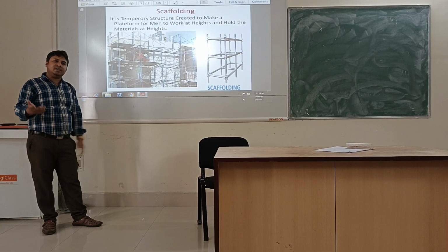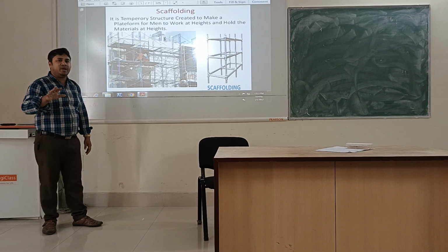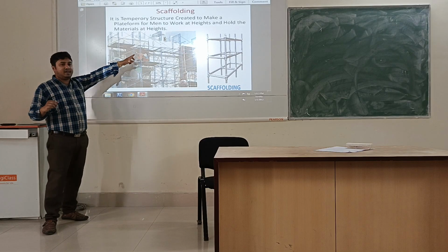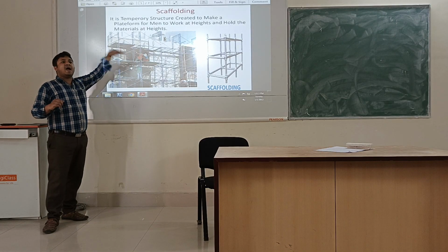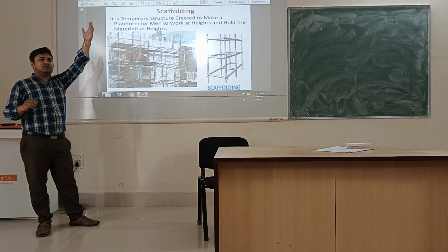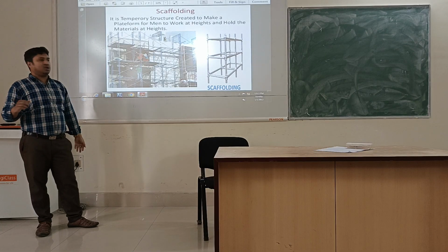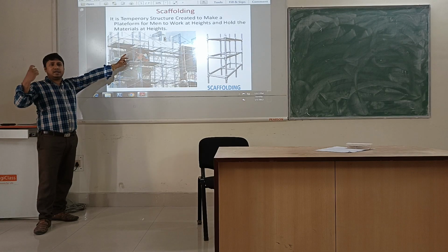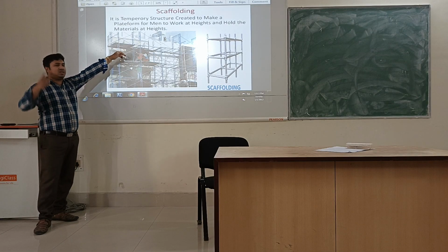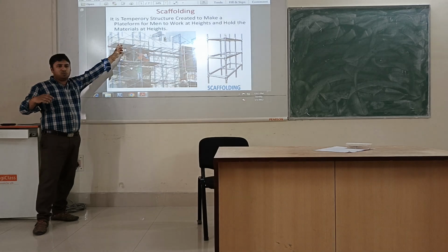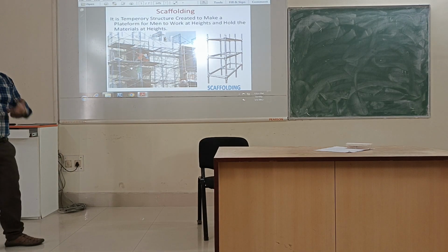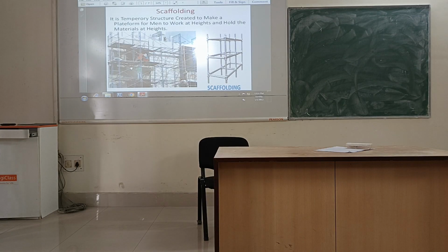What is that? Helmet is very common. Helmet needs to be worn even when he is grounded. I am asking about when he is on the staging at some height. Body harness. Okay, right. So he needs to clamp himself with the body harness to some staging work, where even if he falls, he will be safe there. He will move and he will be hanging by using the body harness. Some safety gear must be worn.